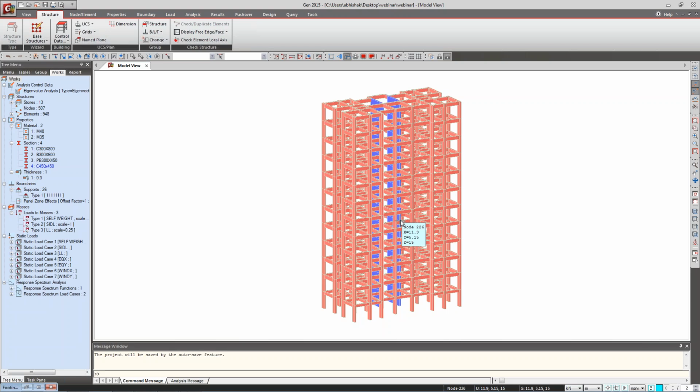One more question asked by Harish Patel: if we model the shear wall, will the meshing option be better? No sir, because we give the mesh to the shear wall only because we want rotational stiffness. But in our software we have inbuilt programming, so there is no need to provide the mesh to the shear walls, because the rotational stiffness is already provided in our software.